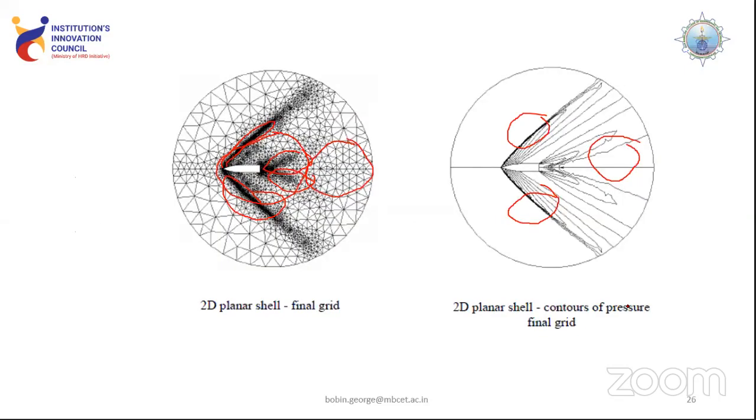So that is basically about the importance of grid. Whenever a physical phenomenon is happening where the effect is anticipated, we create a very finer mesh or grid, and where the effect is normal, we create a normal grid.